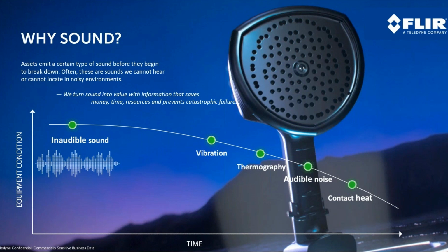We're going to be able to identify sounds emitting from equipment that ultimately indicate a problem or an issue, whether it's a leak, a bearing problem, or a partial discharge problem with an insulator or a connector in the utility space. This is really why sound is a valuable tool for your preventative maintenance efforts, really focusing on preventing those consequences of failure.